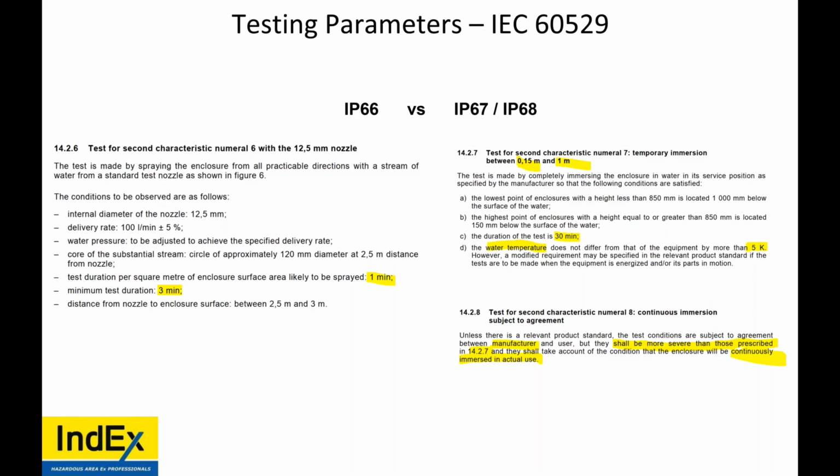What does the canopy affect the IP rating? Will it improve it or not? So I think you're talking about sunshades or rain hoods. That does not improve the IP rating of the equipment. If the hood is not an essential part of the equipment, meaning if it's not tested with it, it cannot be confirmed as to affect the IP rating.